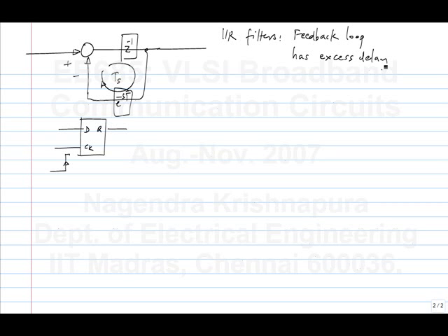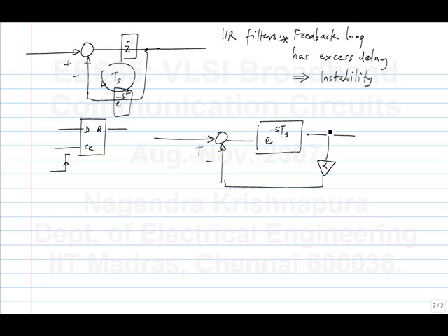You can convert all of the analog signals into digital signals and make a digital FIR filter. And as long as digital circuits are working as they are supposed to, it will be fine. But that is not the regime that we are looking at. Although many of the equalization techniques can be used there, that's not where we are looking. You are looking at some signal and then feeding it back into this. Or another way to think about it is this: the block that you wanted to implement was, I'll write it in the continuous time type of representation, something like this, right? And then you can have more taps. You will have more taps typically.